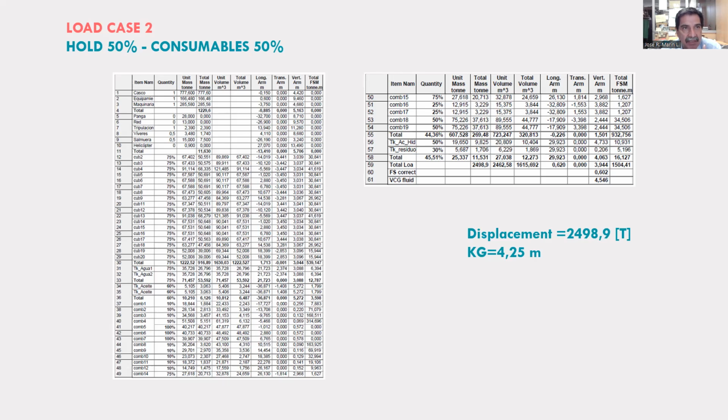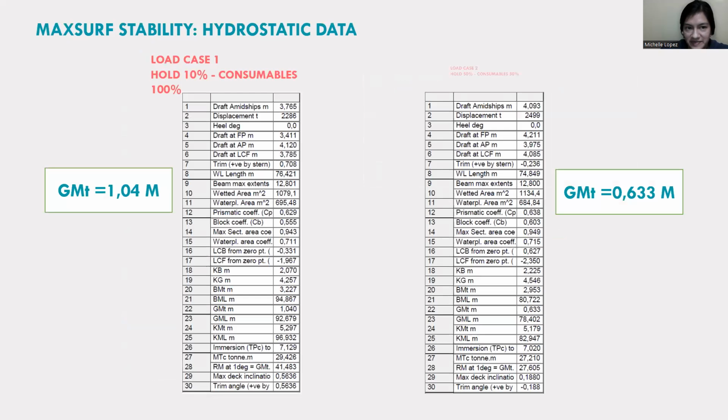So in general, the GM can be considered as a specific parameter. You can compare directly the GM for any ship because it's independent of the size of the ship. So when you present the KG, try to present it as a quotient with respect to the depth of the ship, or include also the GM. Yes, go on, and next slide for the GM.